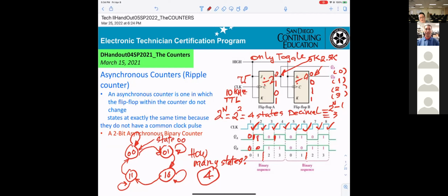You understand in the computer, they have only one master clock, how many gigahertz, sorry. However, inside the motherboard, they're not only using that master clock. They use different frequencies depending on the circuitry. So in order to get a different frequency, they're using a divider: divide by 2, by 4, by 16, by whatever number.